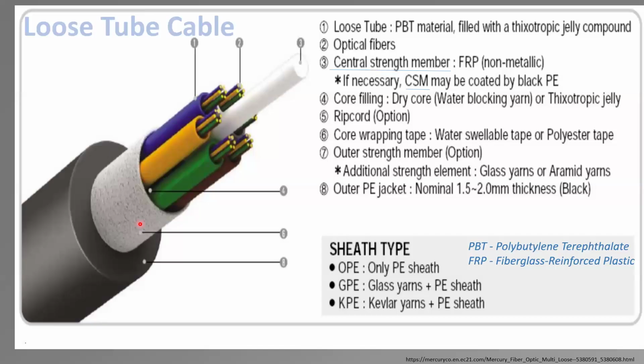High power compressors come into play when it comes to blowing out the water, and then you still have to be really careful, because if the pipe ends up underneath some kind of electrical panel, of course you should not be putting the compressed air on the other end to blow the water out, because you'll be just blowing the water onto the electrical panel.